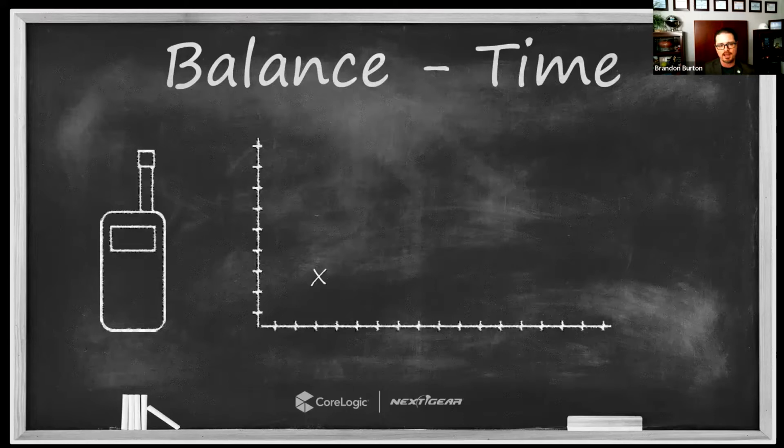And this is an analysis we'll use for more than just humidity, but let's just talk about humidity for a moment and the measurement of that humidity in grains per pound, right? The actual amount of water vapor in the air, not relative humidity, but in grains. And let's pretend for a moment that we've taken this reading at this particular point in time and we've got 41 grains per pound. And then a certain amount of time transpires. This could be a day, this could be hours.